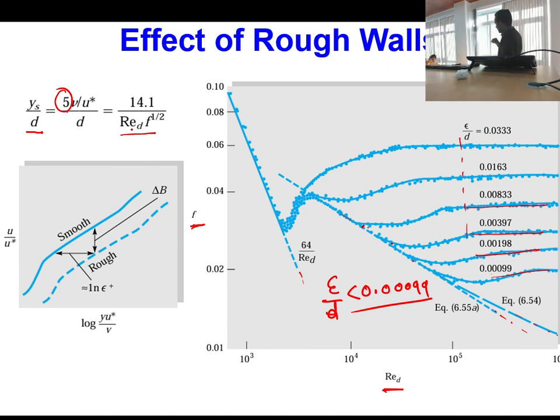But if y plus is small and it is going above the rough portion of the pipe. Okay. In that case, if it is small and it is within the maximum rough portion of the pipe, then influence of laminar sublayer will not come into picture. That's why the deviation will happen at low Reynolds number from smooth pipe correlation. Is this one clear? What I am trying to say, let me show you in the visual manner also.